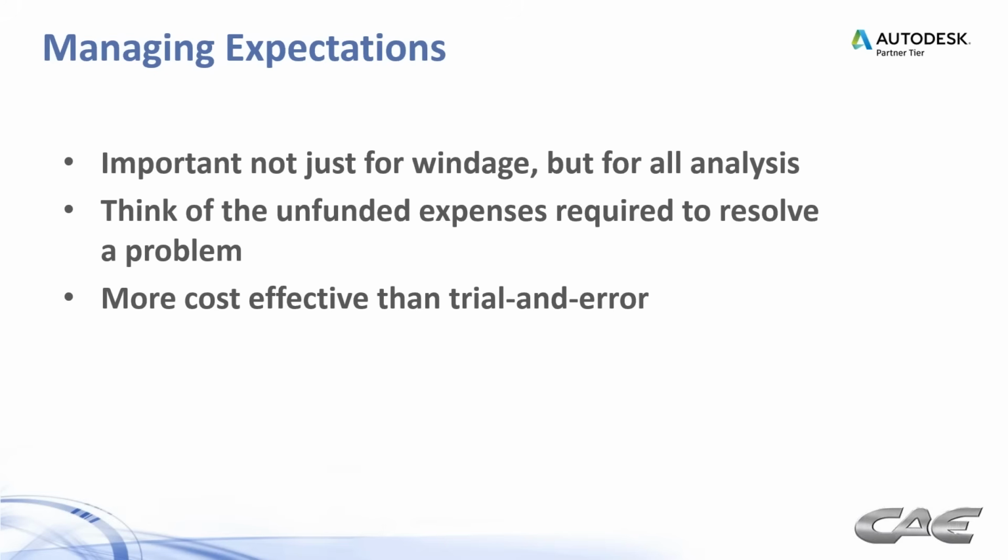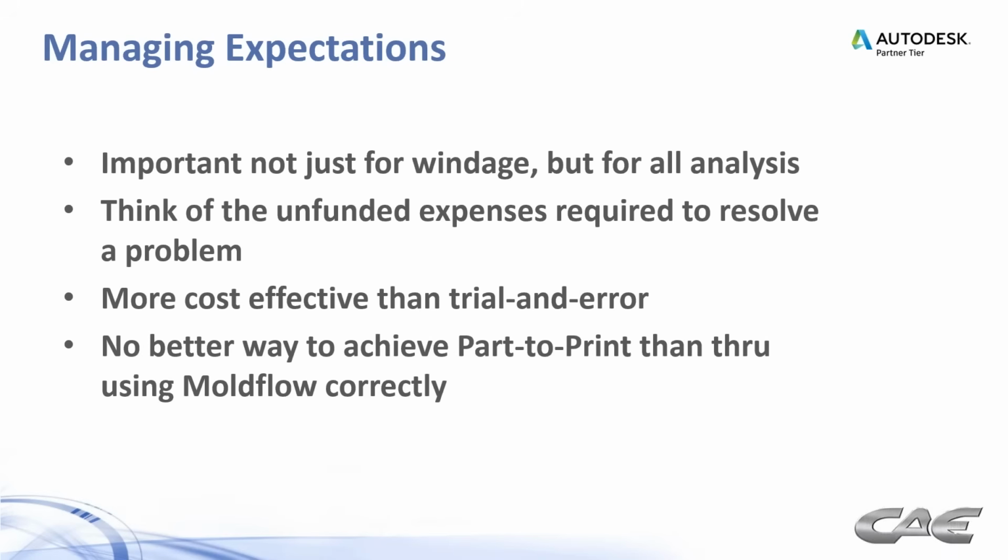And again, it's incumbent upon the analyst to know when to believe the results and when not to believe the results. But in any case, it's way more cost effective than trial and error methods. There's really no better way to achieve part to print than through using Moldflow correctly. And correctly is the operative word there.